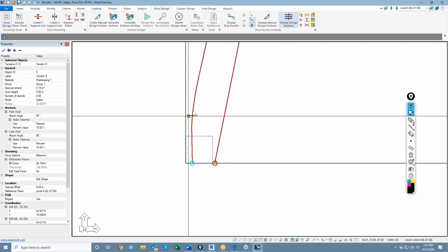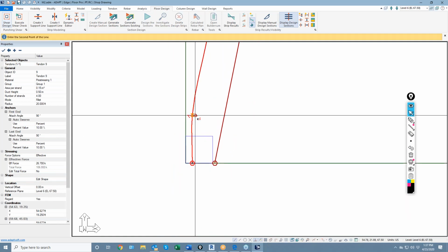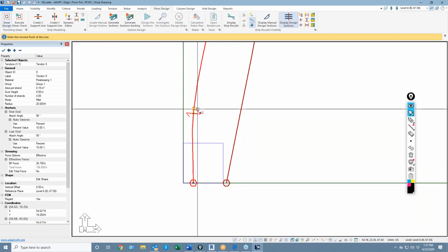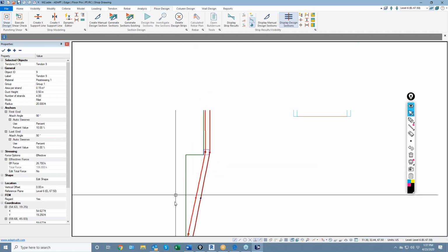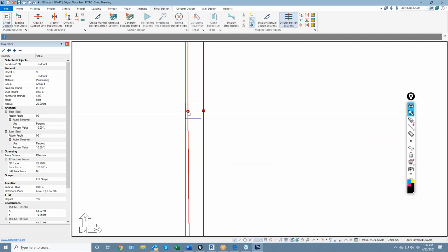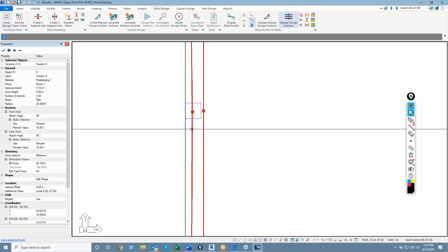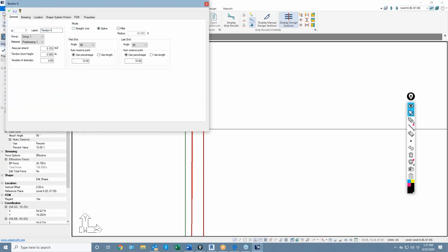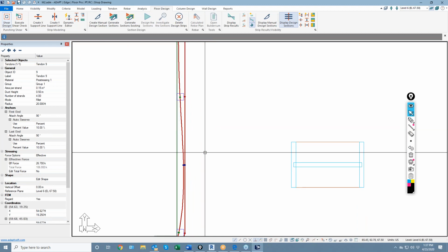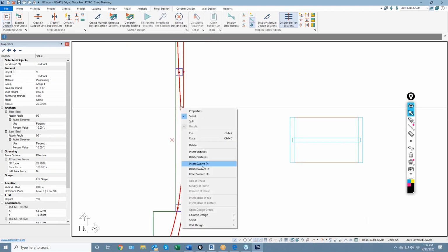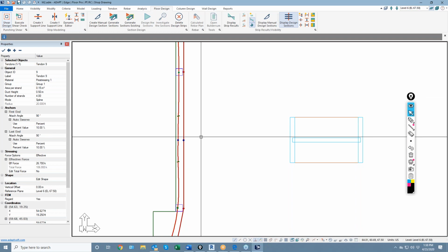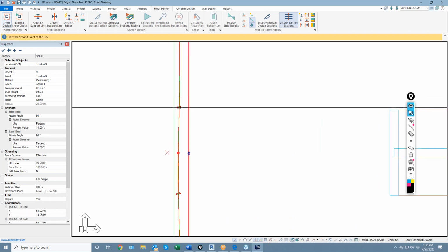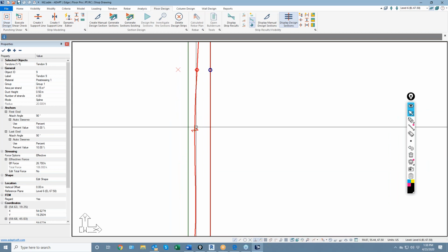There's also a swerve point. If you wanted to move that cable and swerve it here, then you could adjust the curvature of the cable by using these swerve points. And you could always add a swerve point to a span. So if I was to take this back to spline and say, well, I don't want that to kick out this direction, I could just right click, or go to the tendon tab, and we could insert a swerve point, maybe like so, to straighten that out. And then I can control the in-plane sweep of the cable just using those points.